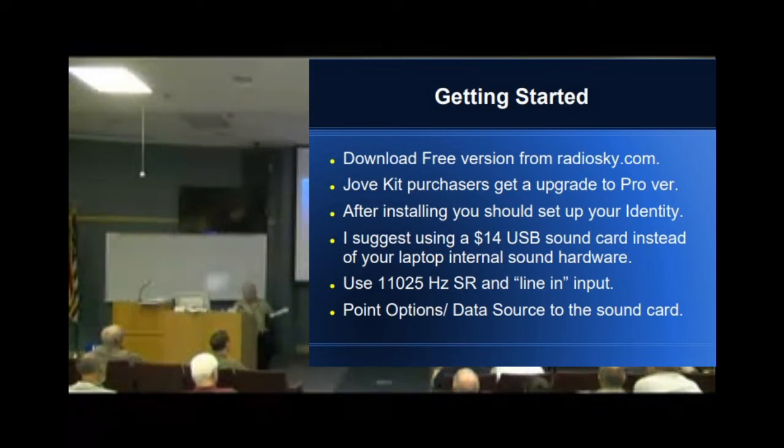And one thing I'd like to suggest to you, that one of the first things that you should do, and lots of people fail to do this because they just want to get going, set up your identity in there. Let people know who you are, where you are. That is what makes your data valuable. Metadata is data about data. And I've gone to a great extent to try to put lots of metadata into Radio SkyPipe files, and please take advantage of that by putting your name, location, that kind of thing in there.